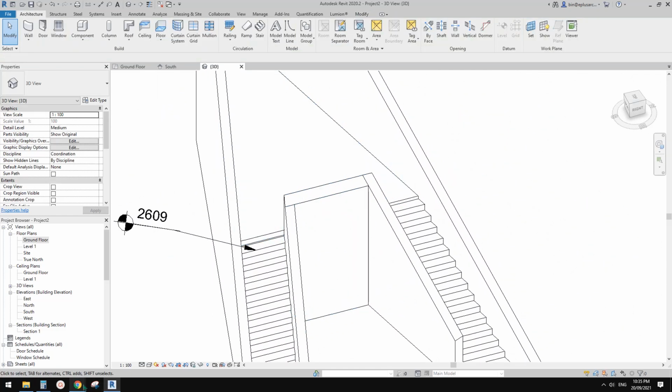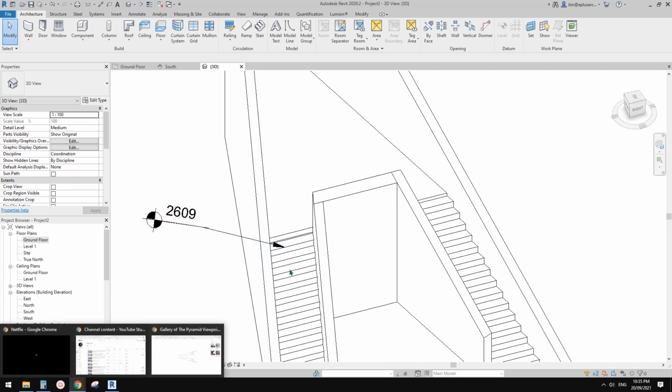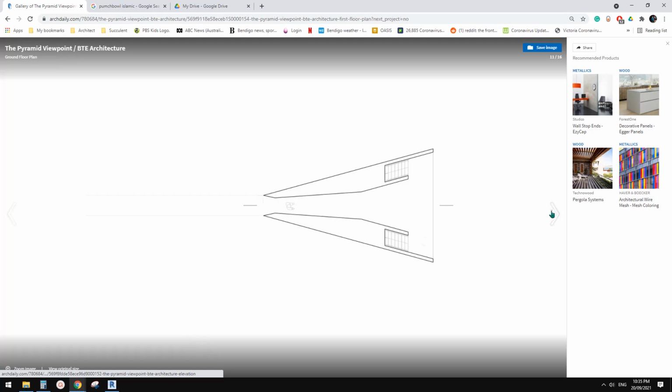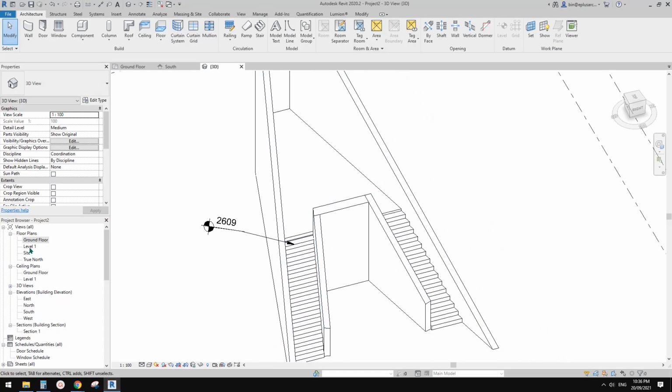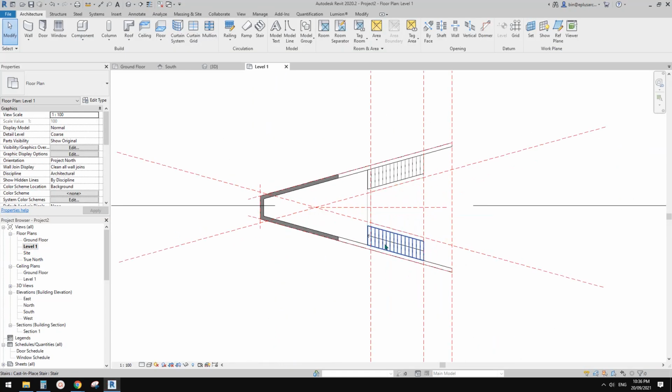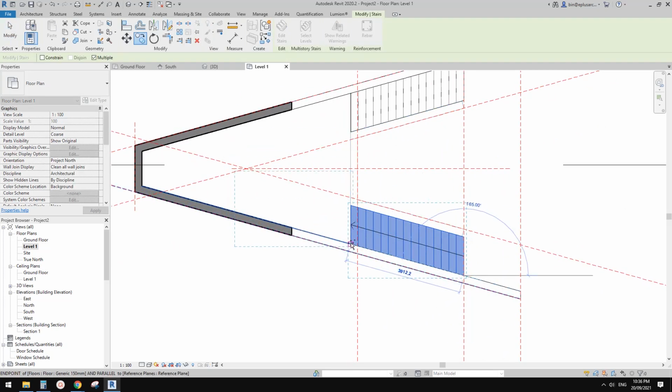And then maybe we go to that image where, yeah. So this is upper, so you will see another stairs, and all these are seating. So what we can do is we can just copy this one up there. So now we can go to up floor level, on which we can select this level, copy this up here.